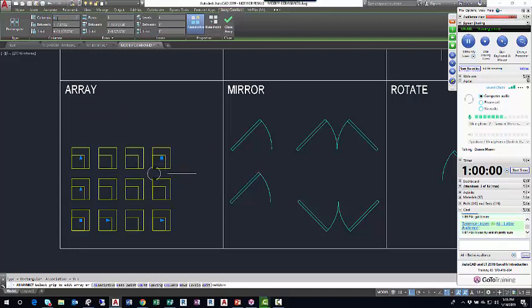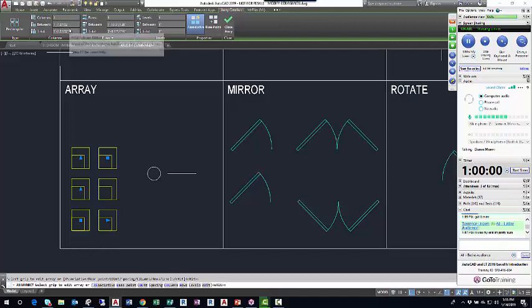So I'm going to change the 4 to 2 and press enter. And that bought me a little bit more room. Right now I have 1'7" and 27/32 of room, or inches, between, or what is that, like 19, almost 20 inches of room between these 2 columns, sort of midpoint to midpoint. If I take that down to, say, 15, all right, and I'll update that. So now that kind of pressed them together a little bit more. I put 1'3" between those 2 columns.